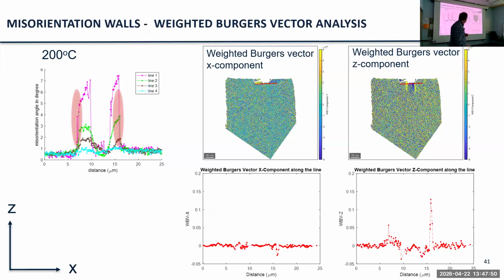And just to show you, this is the high temperature case, again confirming that the deformation field goes less deep. The way I would think about it is that you're pushing this material into the material and it wants to relax, but it doesn't have any mechanism to do that at room temperature, or very little. Whereas at 200, it's much easier. So now the material relaxes, and the depth of penetration of the material you're pushing in is much lower than it was at room temperature when you go up in temperature.